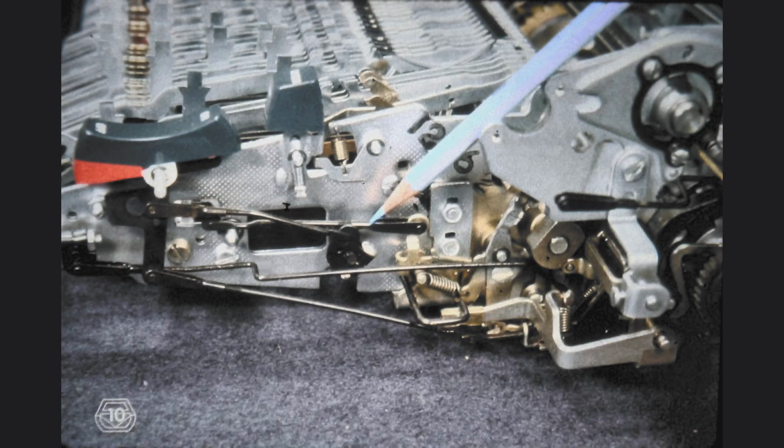On the right side of the keyboard, we find that the velocity control vane transmits its rotation through the indicated link to the low-velocity selector latch, which will also rotate top to the front or counterclockwise. The function of this selector latch is to release a negator-powered or spring-powered mechanism, which will position the roller on the print cam follower into the path of the low-velocity print cam.